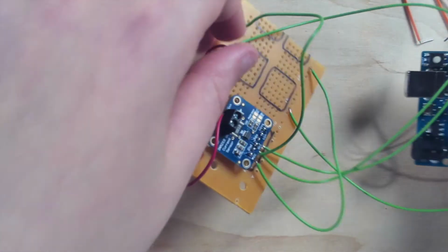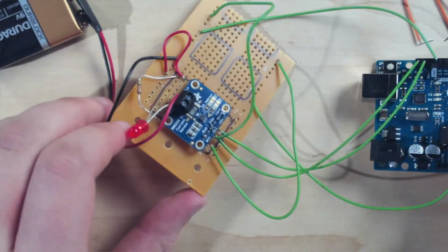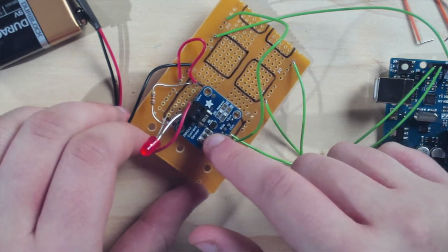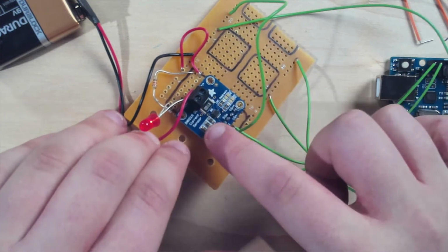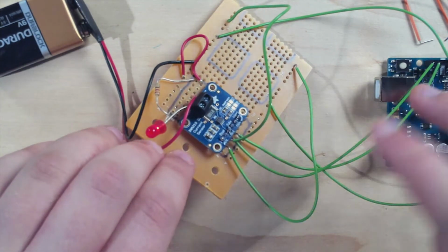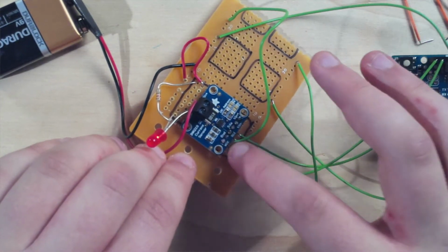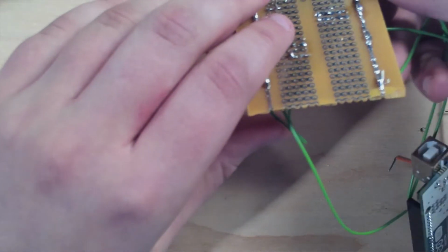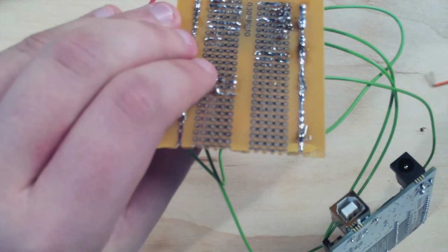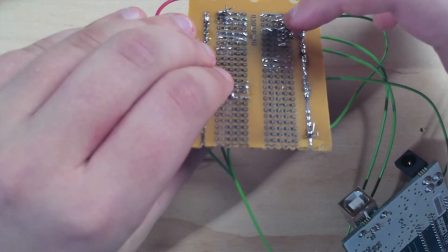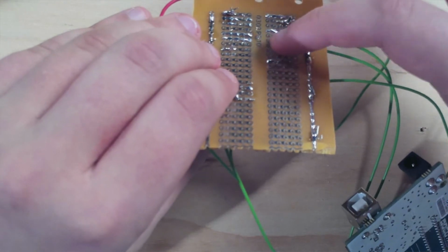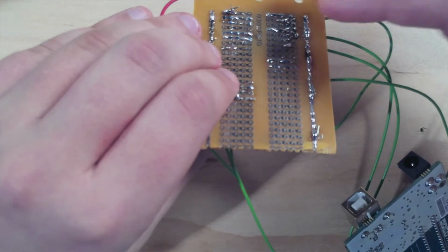Now let's go over what we just did. So we soldered the current sensor together, we soldered it to the circuit board, and had 4 wires going from the circuit board that's attached to the pins on the bottom from the current sensor, as seen here. 2 of them we're not using, but you still solder them in the same row just to keep some balance.